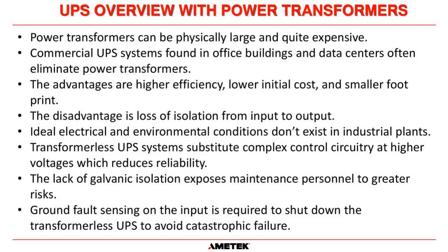Lack of galvanic isolation exposes maintenance personnel to greater risks. Typical ground fault sensing is required to shut down the transformerless UPS to make sure it cannot backfeed the bus, or if there's a ground fault in the 480 distribution.